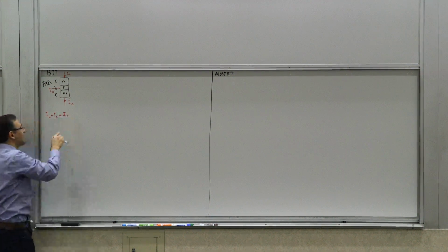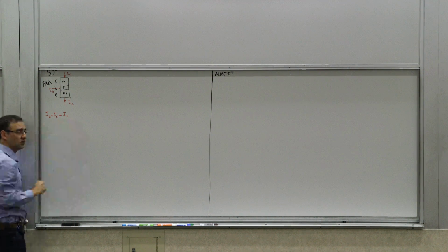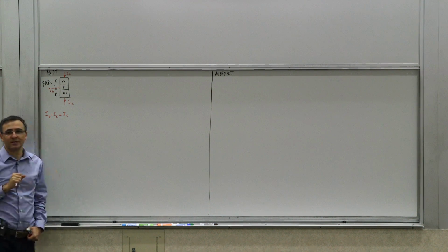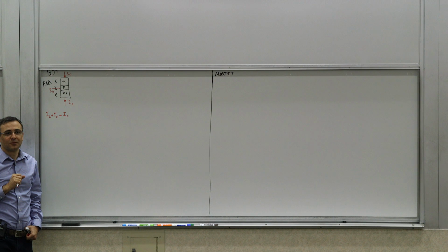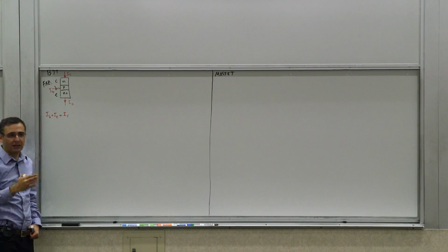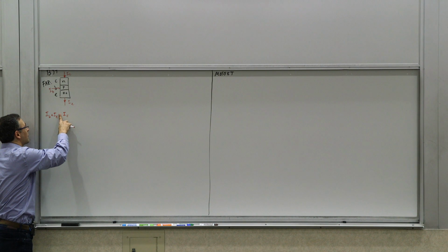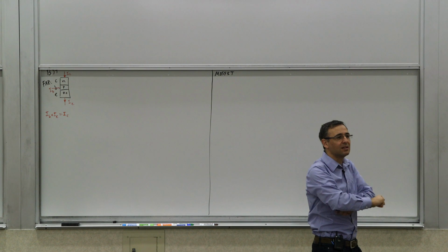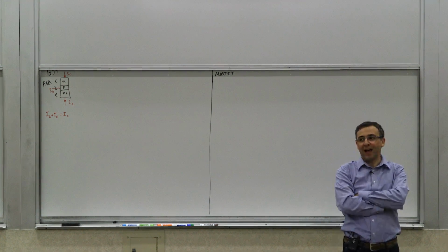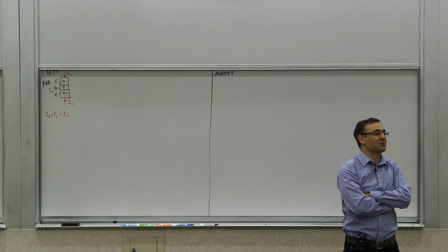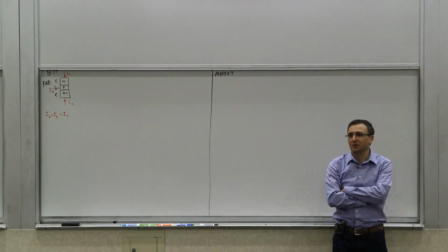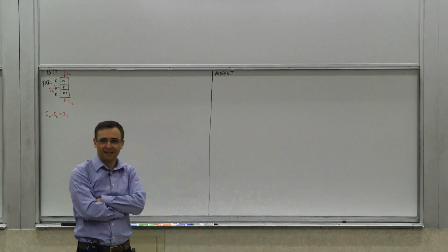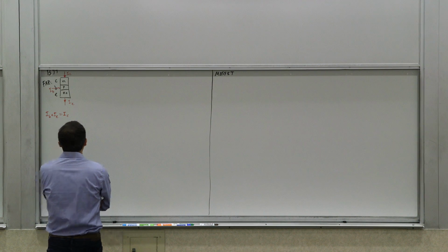Now, this is generally true. Why is this generally true for typical devices that we have? KCL, right? You said KCL. That's correct. But is it true at very high frequencies too? For example, if you're switching the transistor quite fast, would you expect this expression to hold still? Well, how fast is the question? So let me ask you this question. Your answer is correct. Some people were shaking their heads and said, yes, at some frequency this will not hold because there will be some lag and delay between these things. But how high is that frequency?